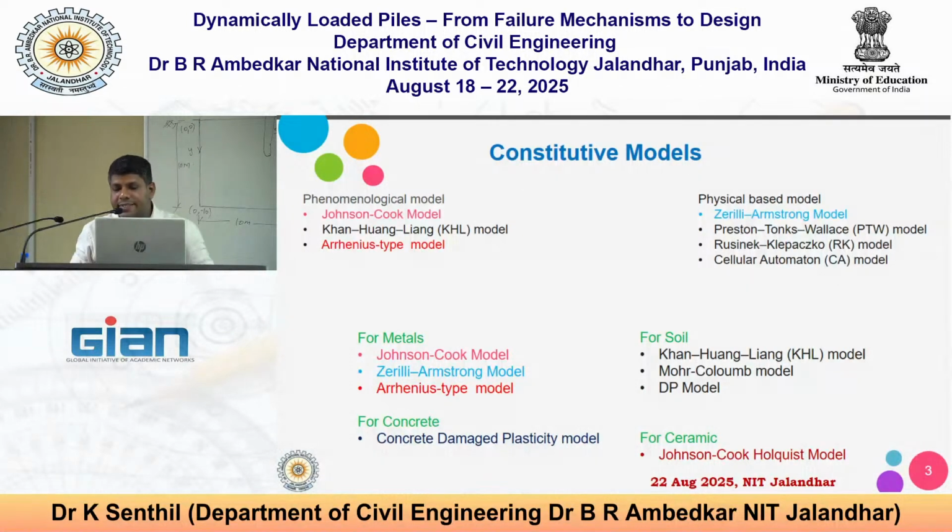Similarly, physical-based models include the Armstrong model and some more, and we have different models specifically for metals, soil, concrete, and ceramic. For soil you can use the Mohr-Coulomb model and the Drucker-Prager model. These are the familiar models. So you have to characterize those parameters very precisely. Now, if you look at this DP model, the Drucker-Prager model,